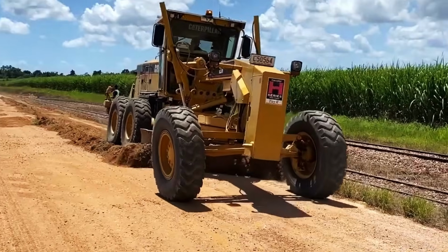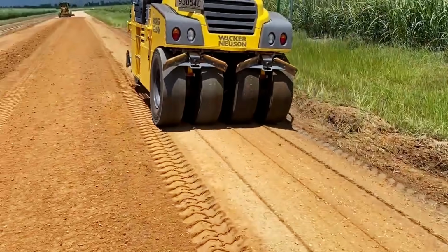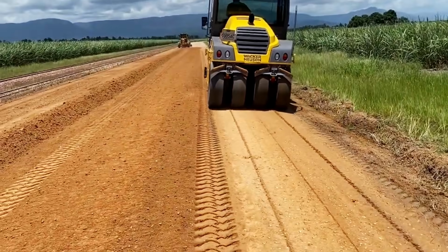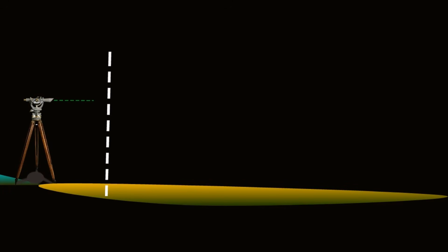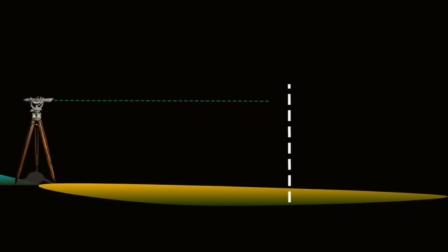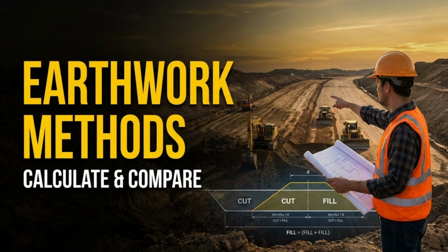After completion of site cleaning, the top surface of the cleaned ground shall be compacted lightly. Then, the reduced levels shall be recorded again before starting subgrade filling. This helps in calculating the quantity of embankment required. Please check, the different methods of calculating earthwork quantity are discussed in another video on this channel. The next item of work is subgrade. It is also known as embankment.